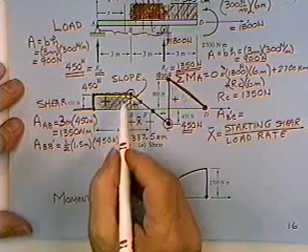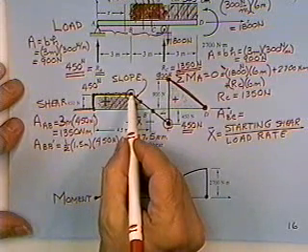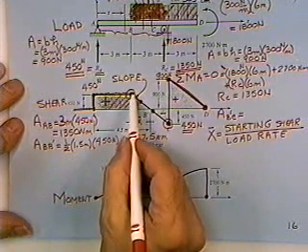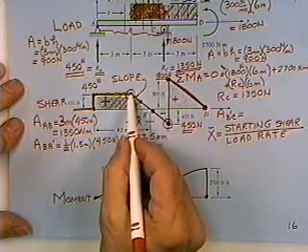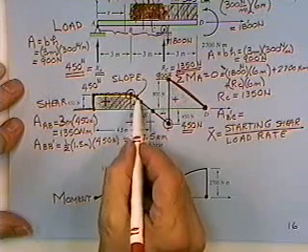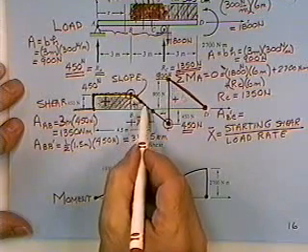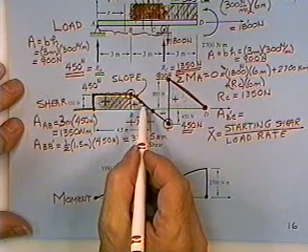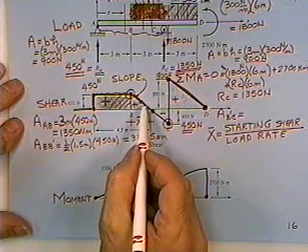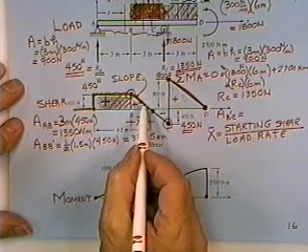The reason that works is because the shear diagram is at this time right here 450 newtons up in the air. The only reason it's going down is because the diagram above it has a bunch of downward pointing little arrows. Those arrows have a downward pointing intensity of 300 newtons per meter.